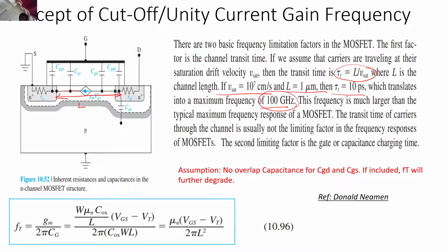Now from where are these resistances coming? Note that this is an N plus doped semiconductor. You must have studied these concepts in the drift current phenomena, the motion of the carriers because of the drift. You must have studied the conductivity, which is something like q n mu n times E if the majority carriers are electrons. But as you can see over here, it is again a semiconductor. Though it is heavily doped, it is still a semiconductor, so this N plus region that you are seeing will have its own resistance. It will cause some resistance.